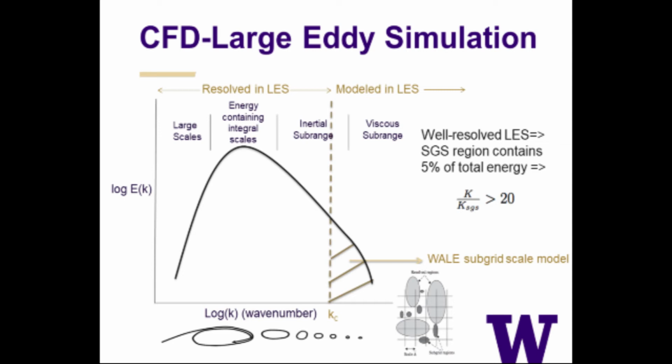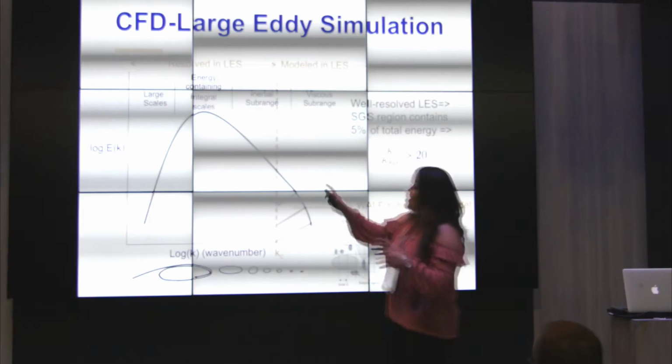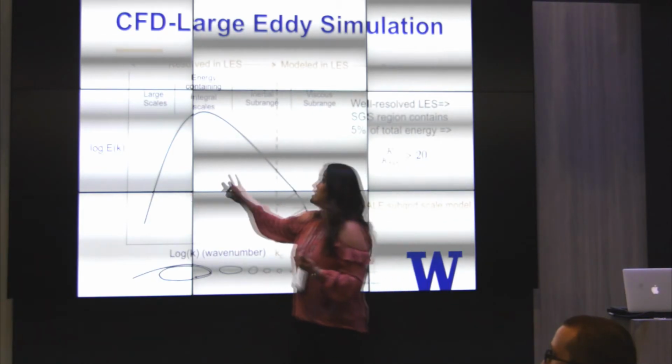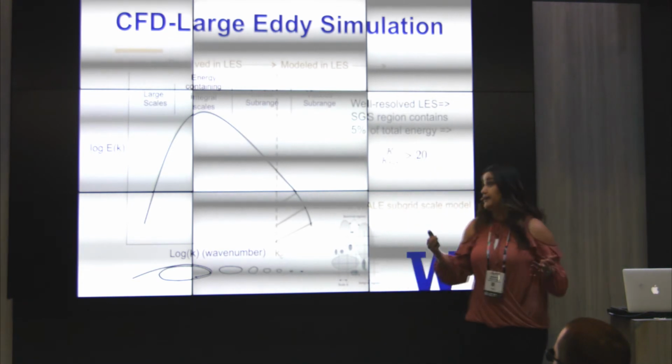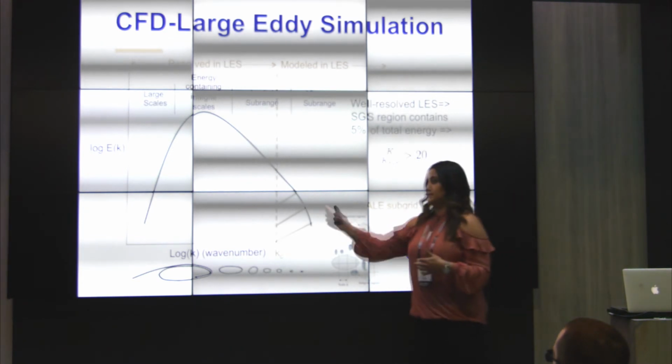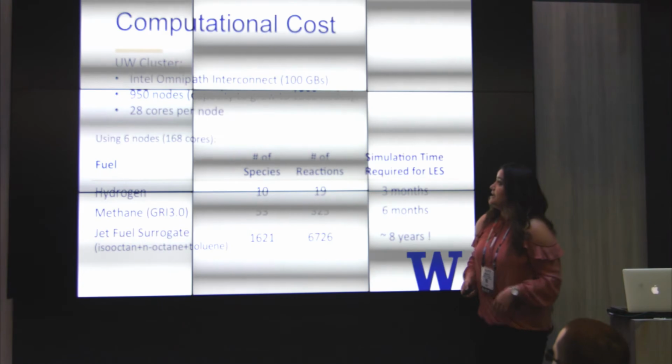And with large eddy simulation, which is getting a lot of attention right now in industry, we're capturing all those big eddies, and we're letting those smaller eddies pass this filter and remodel those. So if we resolve the mesh very well, we're resolving most of our turbulence kinetic energy, but we're modeling just a small amount. Okay?